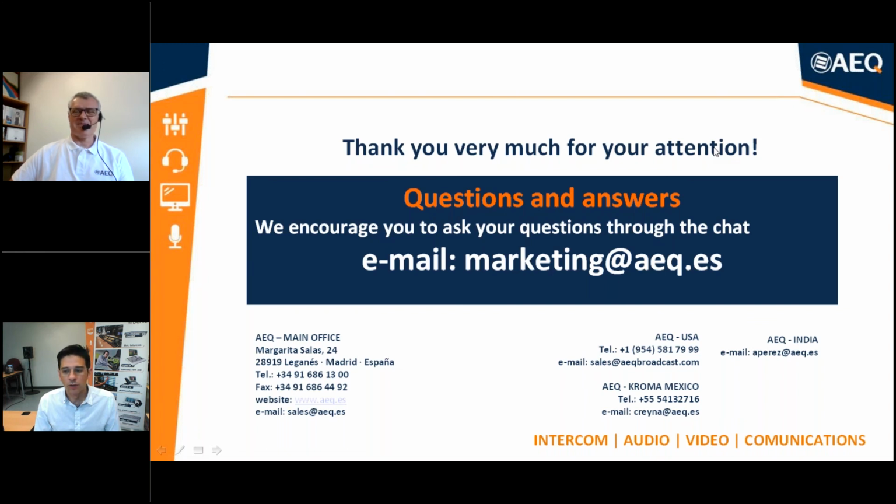In order to send audio, you have different qualities, different bit rates. In a nutshell, we can say that with 200 kilobits per second steady, you can have a high quality stereo connection with full bandwidth using Opus, for example. If you want to send uncompressed audio using PCM, as some customers do, you need more. You need like 1 megabit per second, or 2 if it's stereo, something like that. But typically with 200 kilobits per second, you have a wide variety of modes that will suit every need. Okay.